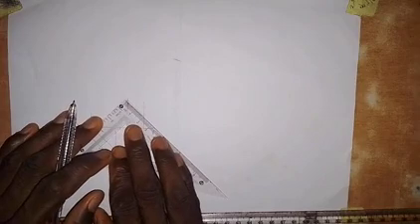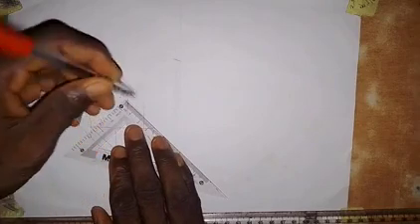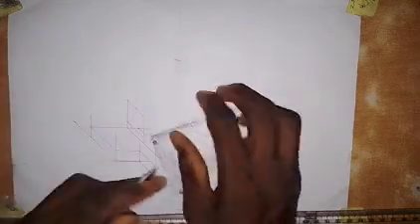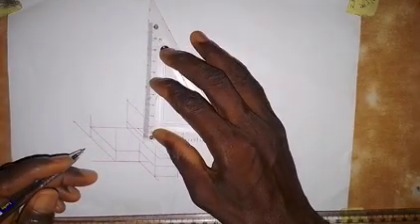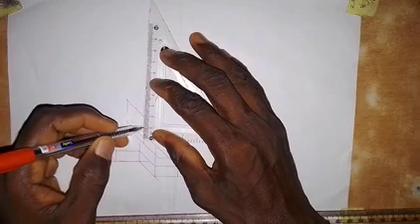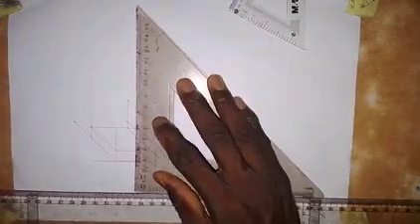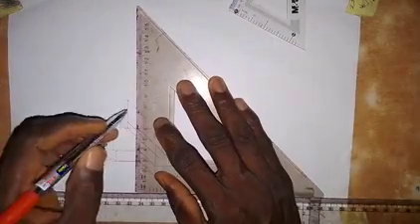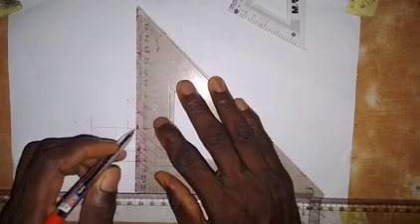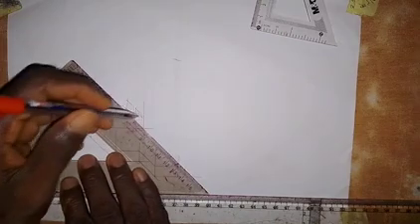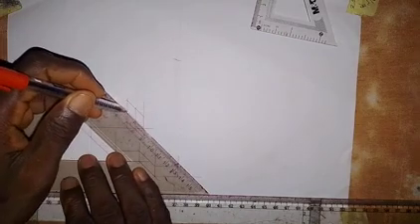So this is an oblique square, so that's what we have there. So that 20, we have to divide it into two equal parts. That is 10, 10. So here we have 10, and then from here we also take a measurement of 10 millimeters up. So here now I'm going to draw a vertical line. So we take down a vertical line. Okay, then with 45 degrees, we transfer this point to the other side like this.